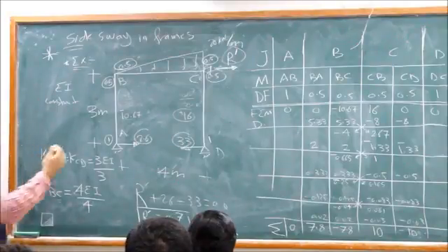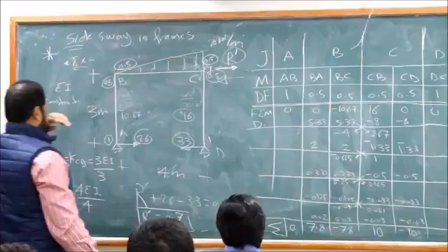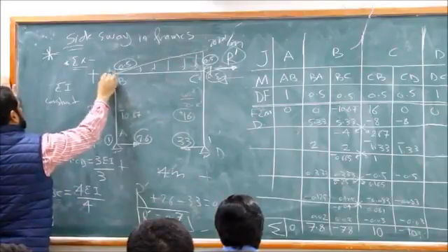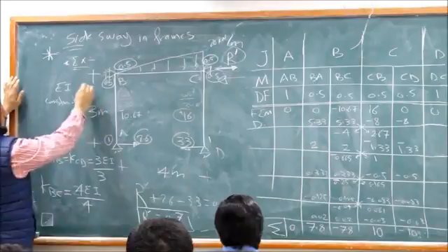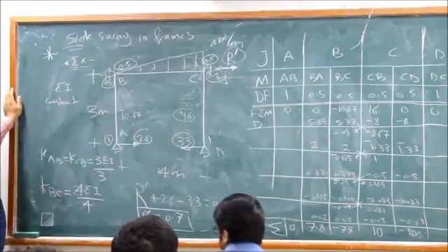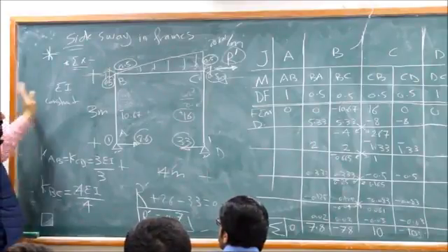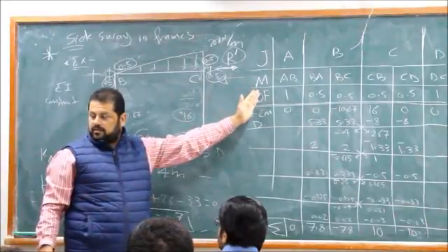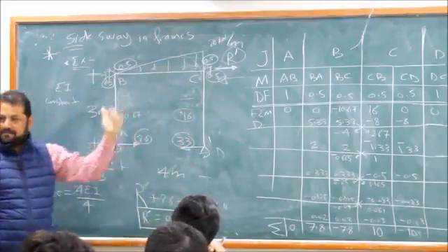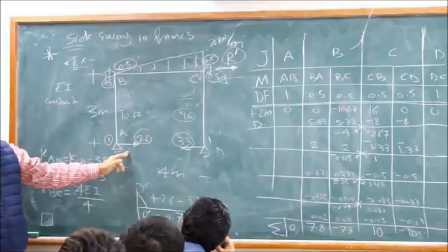I'm expecting the reaction to be this way. This goes this way. We have it here. So this one will be this way, right? Doctor, maybe because the reaction prevents the sway, so it tries to prevent the sway to the right, so the reaction goes with the sway to the right? Then we have 3.3 here, the resultant of 2.6 and 3.3 here, okay, and R also must be here, right?